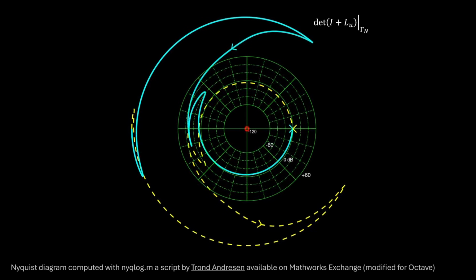obtained. It is necessarily a closed contour that is supposed to be axisymmetric about the real axis. The asymmetry in the crescent shape, I suspect, is due to some numerical error in evaluating the transfer function or the resolution of the points defining the D-shaped Nyquist contour. This was not further investigated, but otherwise the diagram is symmetric.